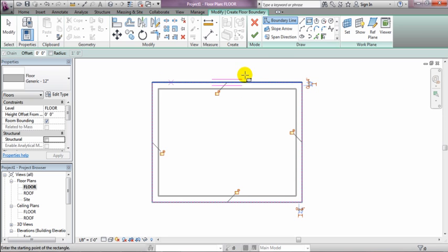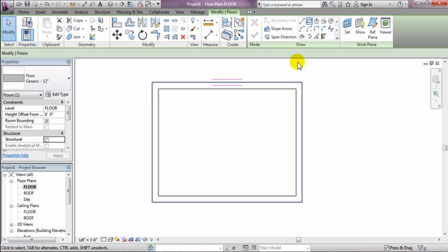I can also draw lines individually to make the floor as well. But basically, any way that you can make a line going all the way around this thing without any overlap. You don't want any lines poking off the edge or not connected. If you ever have any lines that aren't connected, then it's not going to be good. And then we have an X and a check. The X is going to say, no, I want to discard this floor and start over, and check is, yes, I'm happy with the floor, I'm going to check it so that it's all good.